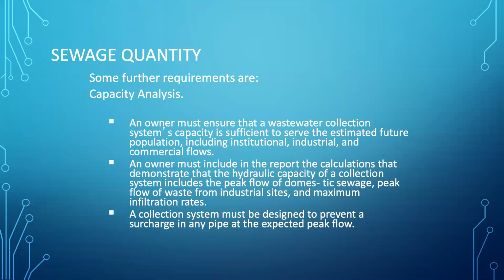Some further requirements, in at least Texas, is we have to ensure that the capacity has expansion capability to be able to serve into the future. And the hydraulic design has indeed included peak flow of domestic sewage, peak flow of industrial sewage, and any maximum infiltration rates that can be estimated.